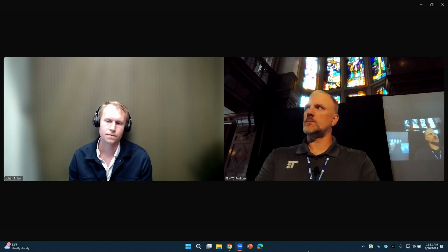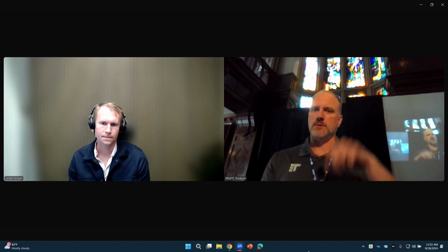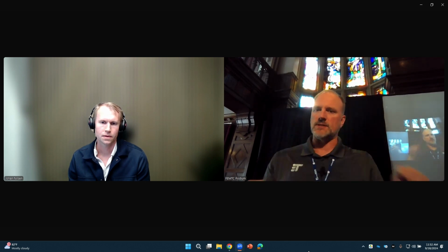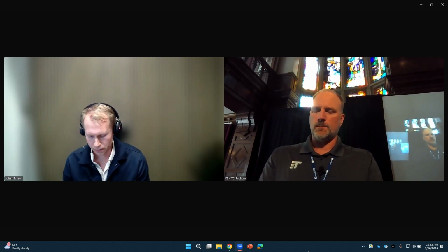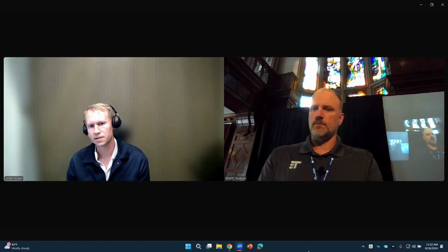Okay, thank you. And for the CO production, did you integrate the area under the curves of both experiment and simulation, and was it essentially the same sort of mass production, but one looked like a very narrow and tall spike and the other one was wider and shorter? Well, when I used the two-step option, the peak was the closest to the experiment, but the total mass spread was slightly underestimated. Okay. Using the two-step option.